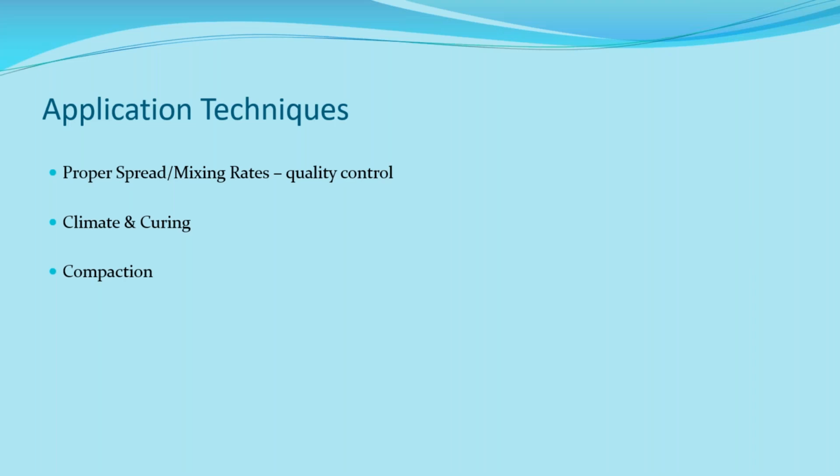Like I've said, if you have rain predicted or if you're anticipating a large storm coming in, you may want to put it off until after it's done. And with every one of these techniques, compaction is critical. Make sure you have a good subgrade and then also compact your surface material. Make sure it's compacted solidly and that you've mixed the material sufficiently.